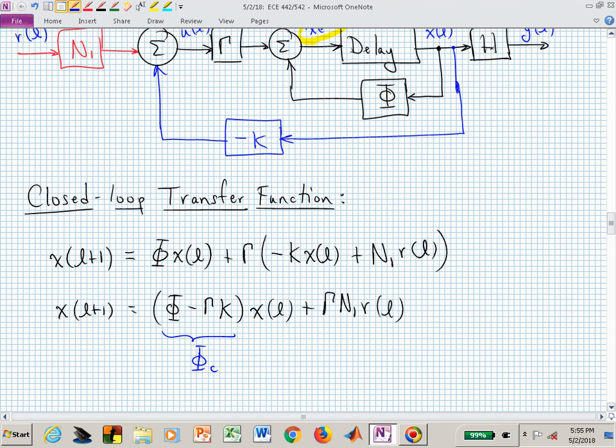If you wanted a certain set of dominant poles, you could pick those two based on performance specifications: percent overshoot, settling time, peak time. And maybe put the others inside that in terms of concentric circles so that the two still dominate. An easy place to put those is at the origin. Those are as fast as you can get.